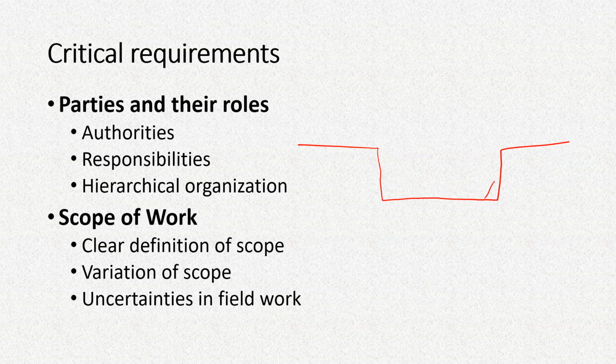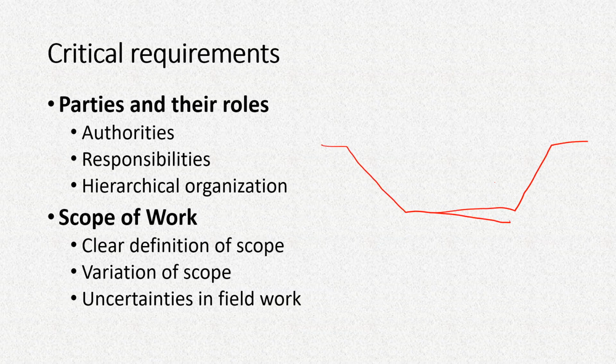But if the field survey is not very detailed, then you will not know about the soil conditions, and when you go to the field, you may find that instead of cohesive soil, you are encountering cohesionless or sandy soil. In that case, this kind of a cut cannot be made in the soil, and you have to make a sloping cut.